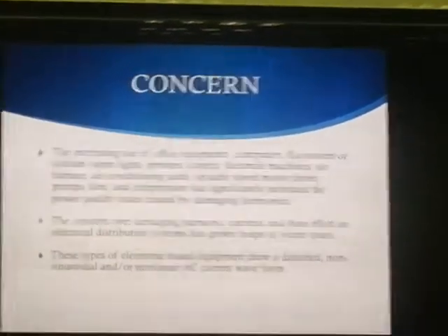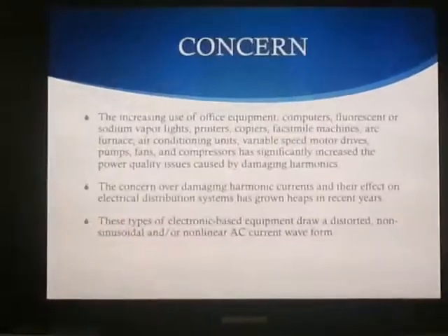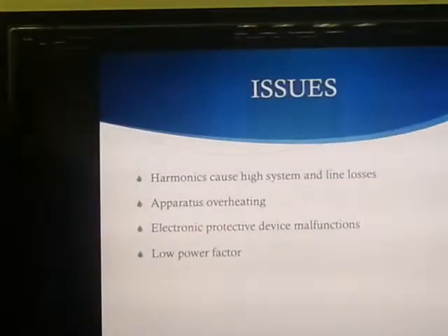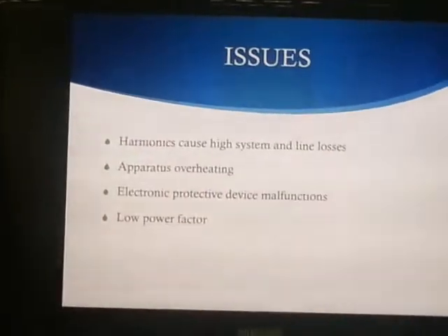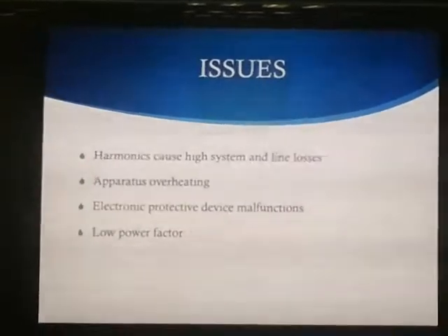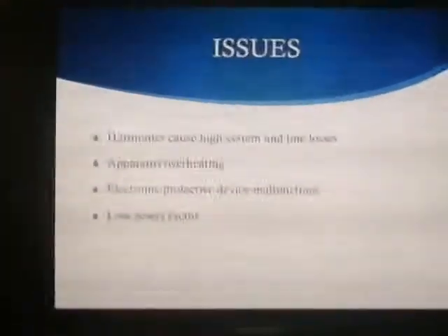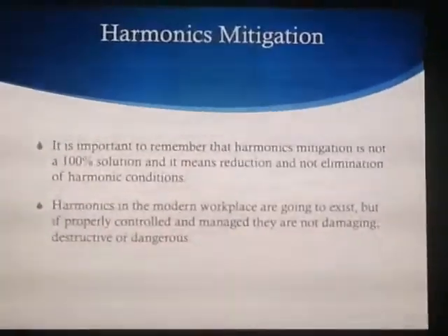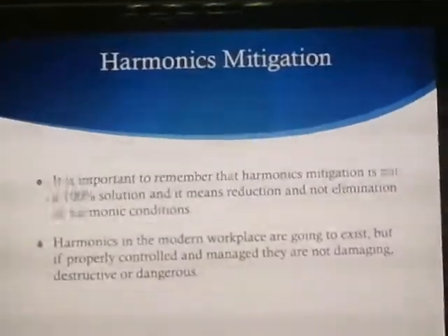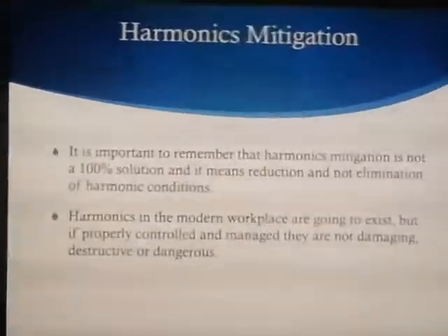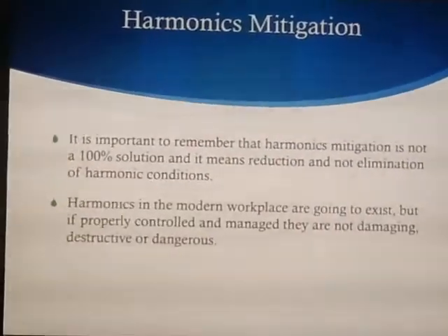These non-linear loads give rise to harmonics, and these harmonics cause issues in the system. Some of the issues are unbalanced voltage, overheating of equipment, electronic protective device malfunctions, as well as low power factor. As power engineers, our role is to reduce these issues so that we are able to achieve maximum output at the load end.